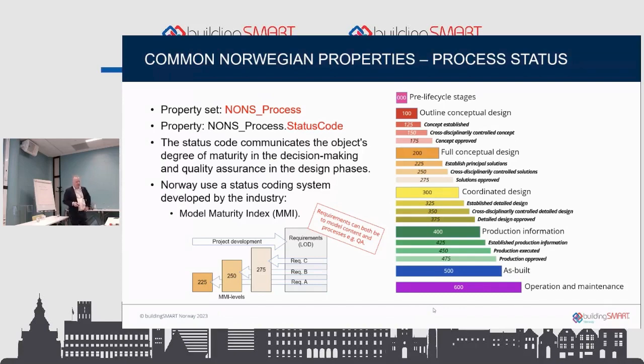Very often this is identified on the volume. If you remember, I said in bigger buildings you have controlled volumes. You say that this east wing or this floor or this building story is one volume that we do the checking on, and when we have done the checking and say now it's okay for the next stage, it can get a next level.